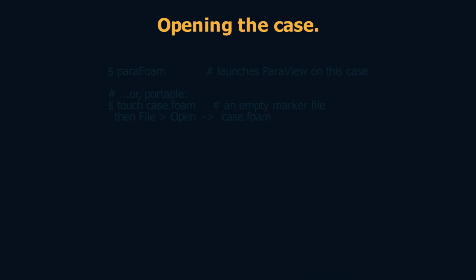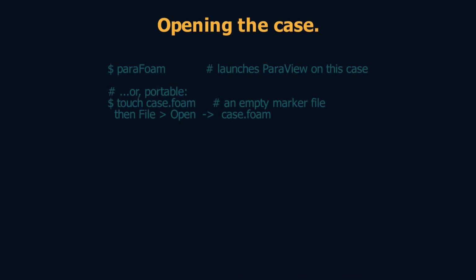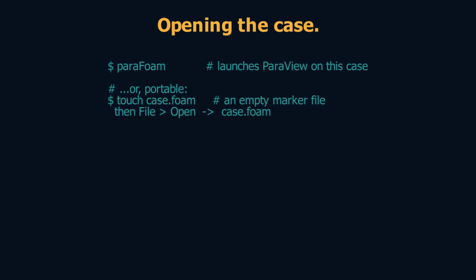Two ways in. The command paraFoam launches ParaView pointed at your case. Or make an empty file ending in .foam and open it directly. The .foam trick is worth knowing. That little marker file is all ParaView needs to recognize and load the whole case, time steps and all. It works anywhere ParaView is installed.